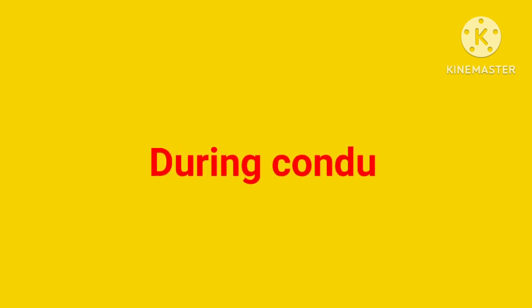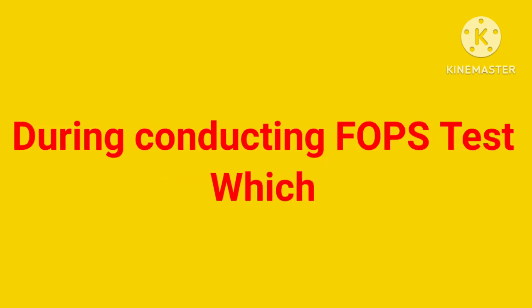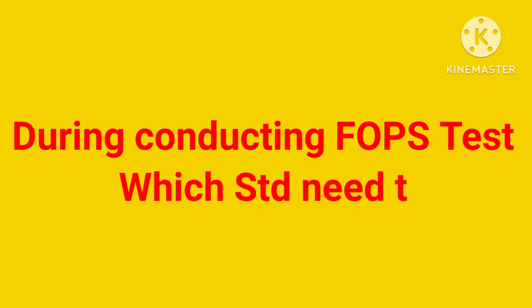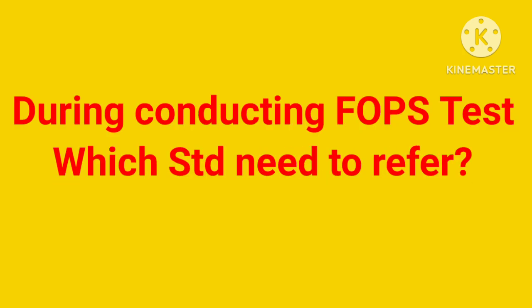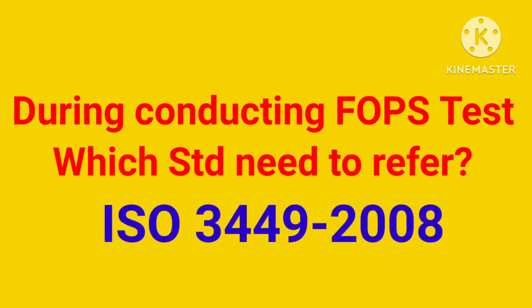For conducting the FOPS test, which standard needs to be referred to or followed? We need to refer to ISO 3449:2008 for the FOPS test, the falling object protective structure test.